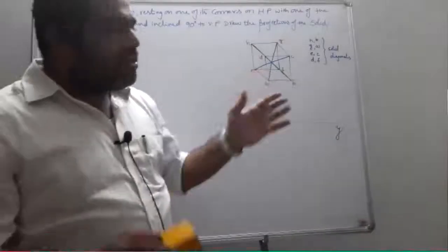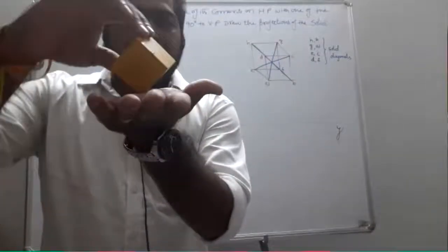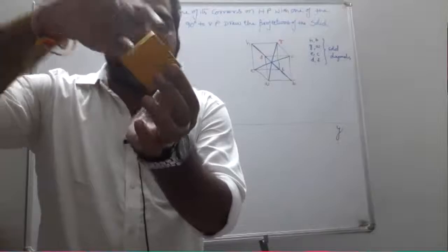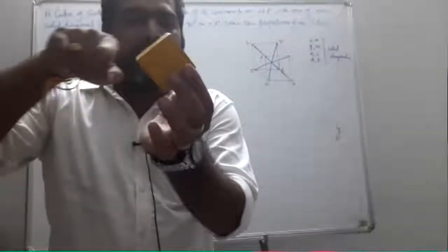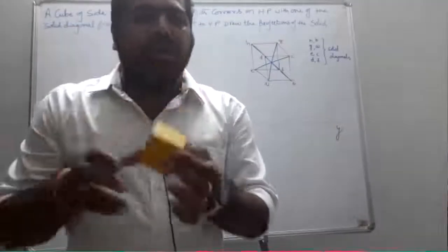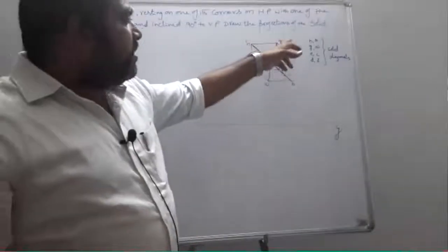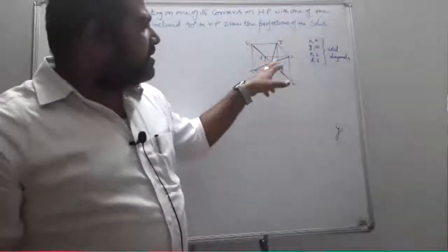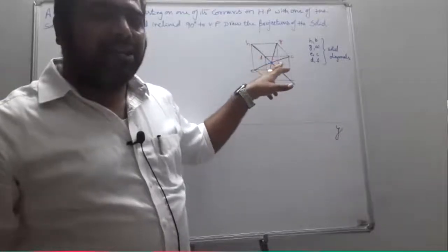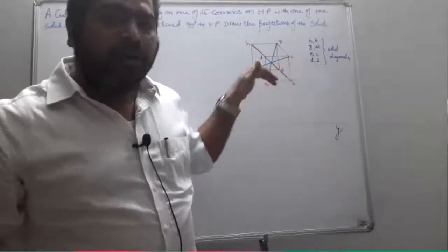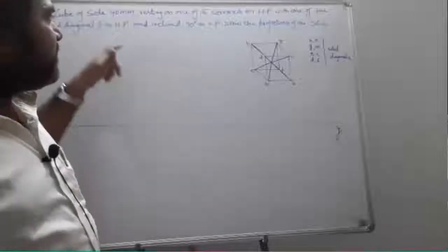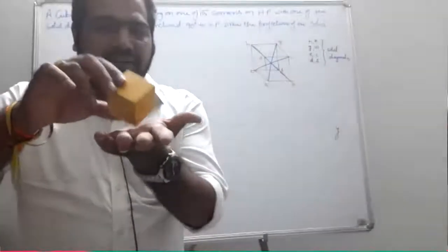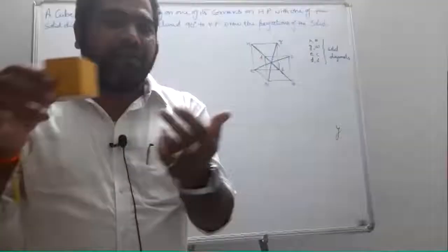When your solid is resting with its corner such that the solid diagonal becomes horizontal, let us say either HB or GA, EC, DF are the solid diagonals. Let us consider any of the solid diagonals and that solid diagonal should become horizontal. So directly he is not supposed to give the axis inclination in the first stage, but that is for the second stage.